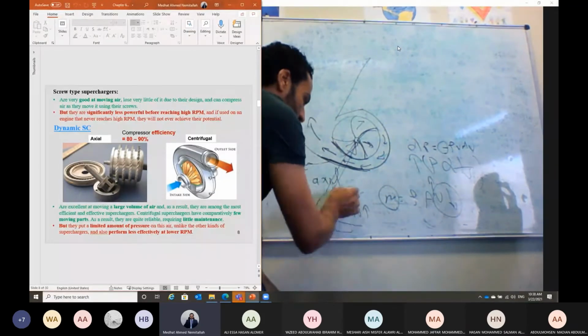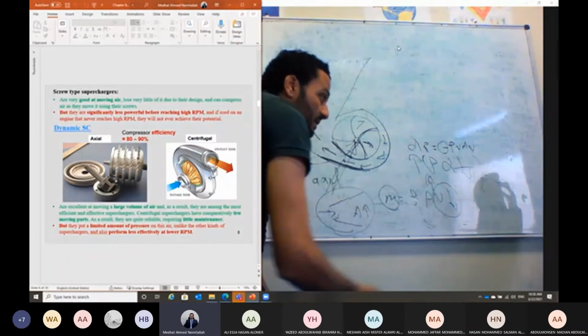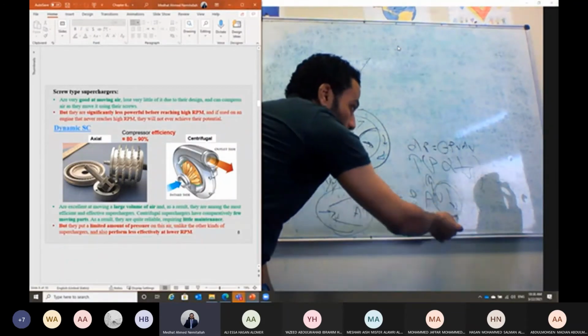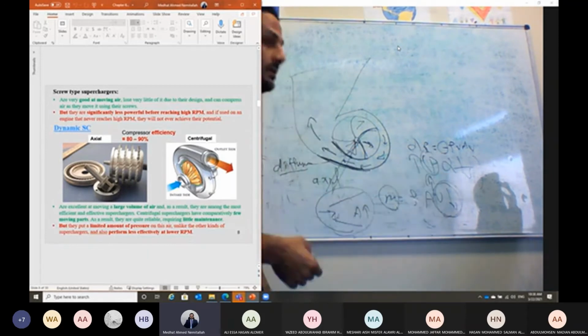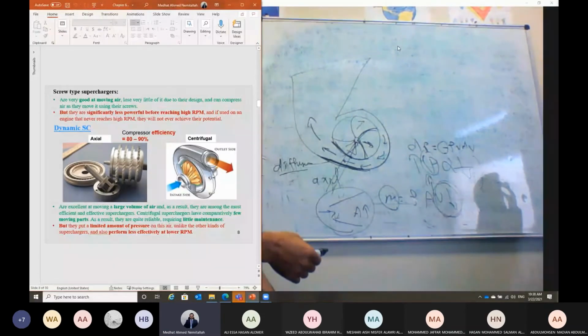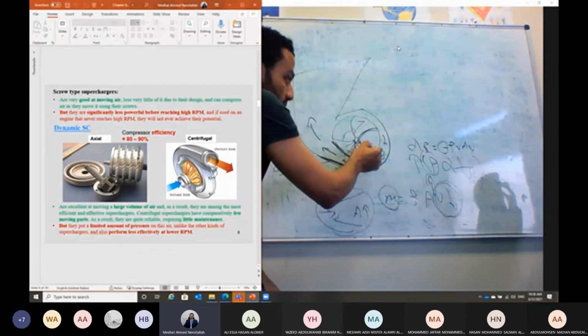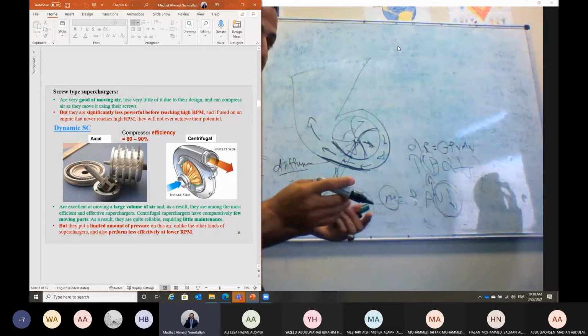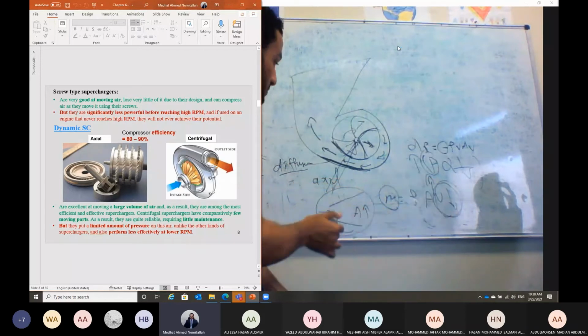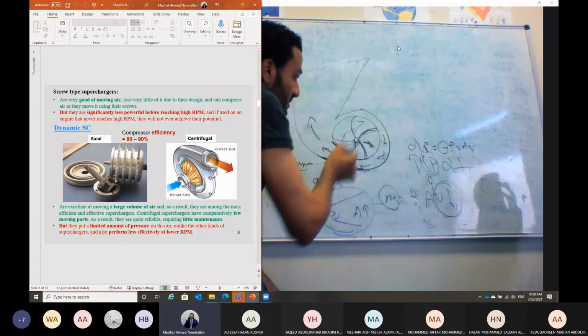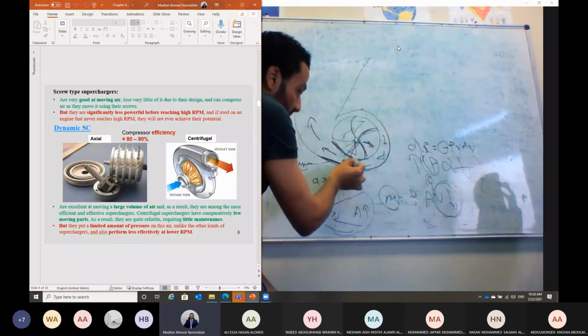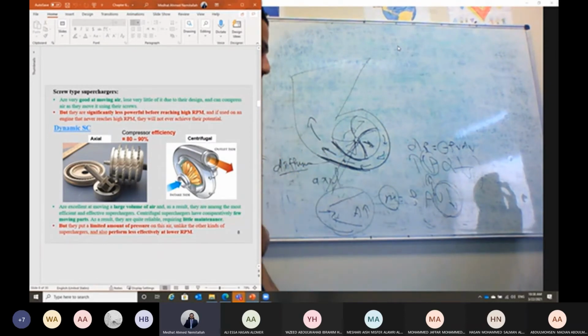Like if we have a diffuser shaped design, if the area is increased in the flow direction, the velocity of the flow will be reduced, and the pressure will build up within the system. And this is the idea of the compressor. We can generate a tangential velocity component through the movement of this impeller, this shaft. It will force the air to go between the blades. The design of the blade itself takes the area of a diffuser, so the area in the flow direction should be increasing, and also the clearance between the impeller and the outer casing is increasing. It takes the shape of the diffuser. Then the velocity will be reduced and the pressure will build up within the system.